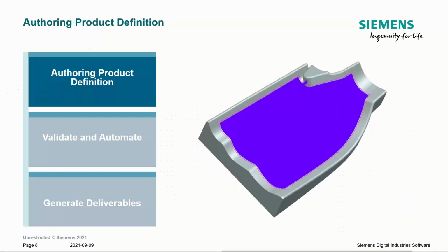So I wanted to take a few seconds to describe this before we go into the product. So here we can see a large purple colored area, violet color. This is what I would consider a full body coverage. And for this example, our design is going to have 3 full body plies. So we create an overlay zone which has just that defined on it. Next, I define 2 more zones which each have core and film adhesive. So we have 2 more pieces of material dropped on top of those previous full body plies.